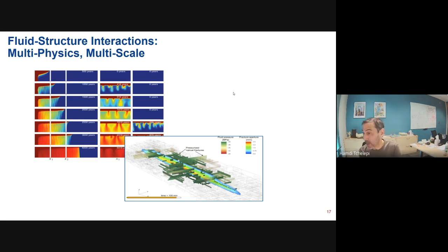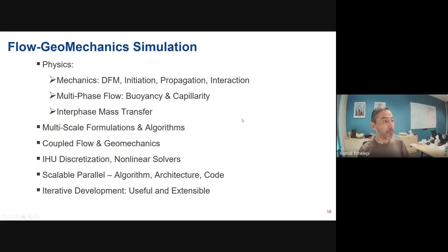Into a subsurface you have limited information about. Into a system that is very likely highly fractured, and you may even want to induce the fractures in order to create a permeability to put away the CO2. So now you're talking about fracture dynamics, fluid mechanics into a heterogeneous subsurface formation at scale. So the mechanisms become very daunting to model at these scales. You have to worry about the fractures, their initiation, their interaction.